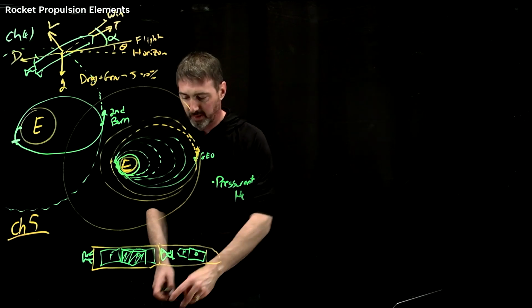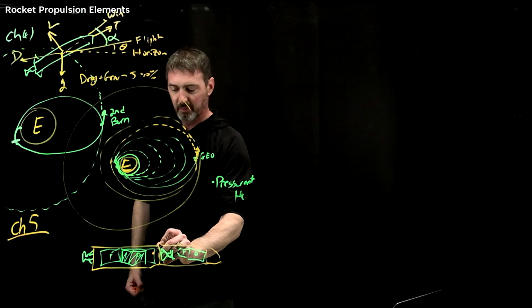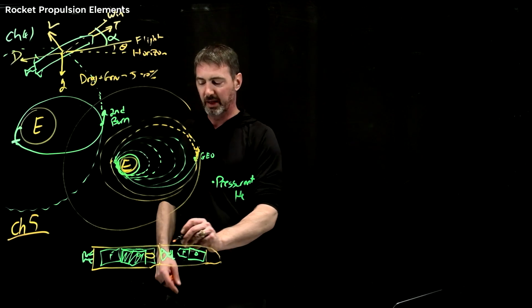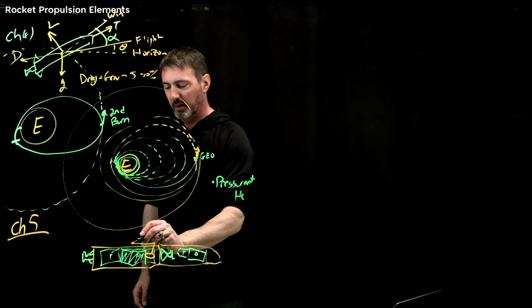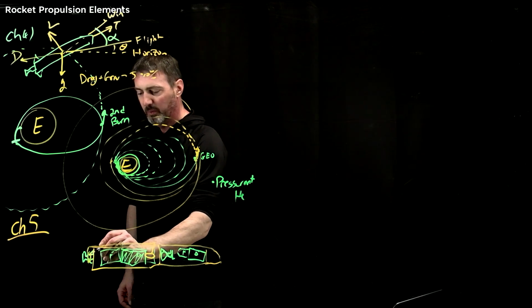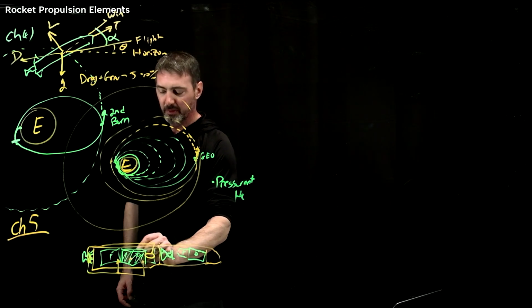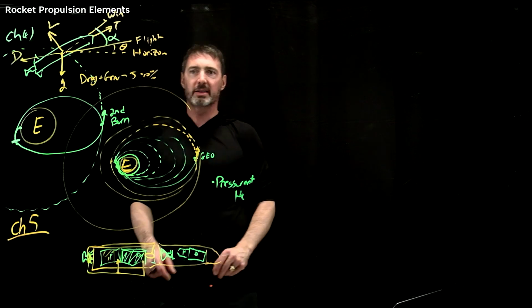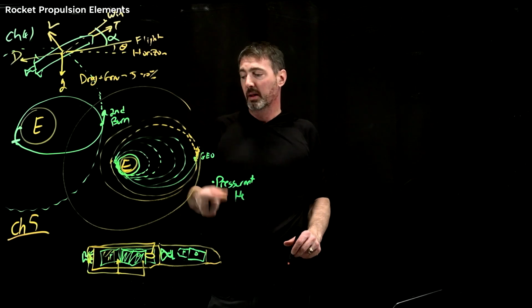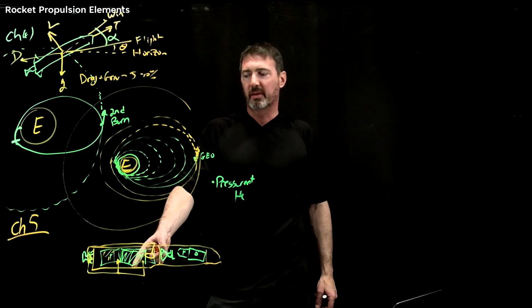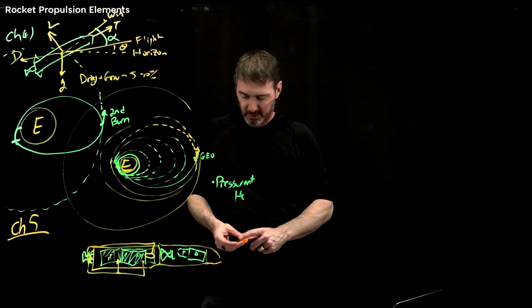And so a lot of times, at Virgin Orbit, we actually stuffed our helium bottle inside of the liquid oxygen tank. So it was cryogenic, so it kept the helium very, very dense. And then we would run a line down to the engine to warm up the helium, and then we would come back and insert helium both in the fuel tank and in the ox tank, so that you're refilling those tanks, right? So as you're draining, you get a backfill. Otherwise, these get pressure locked and things like that. Like your turbo pumps are going to need some pressure. Okay, so you've got to carry pressurant.